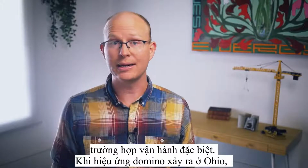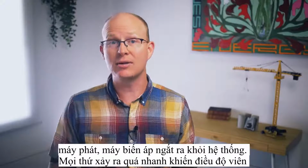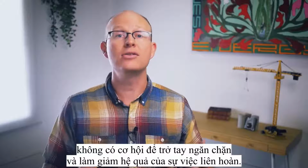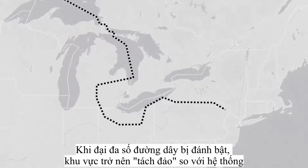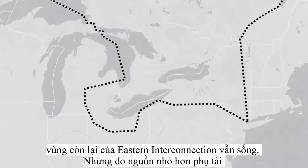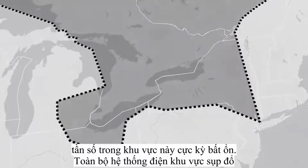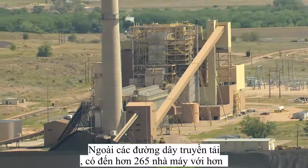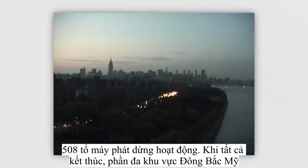Once the dominoes started falling in the Ohio area, it took only about 3 minutes for a massive swath of transmission lines, generators, and transformers to trip offline. Everything happened so fast that operators had no opportunity to implement interventions that could have mitigated the cascade. Eventually, enough lines tripped that the outage area became an electrical island, separated from the rest of the eastern interconnection. But since generation wasn't balanced with demands, the frequency of power within the island was completely unstable, and the whole area quickly collapsed. In addition to all the transmission lines, at least 265 power plants with more than 508 generating units shut down. When it was all over, much of the northeastern United States and the Canadian province of Ontario were completely in the dark.